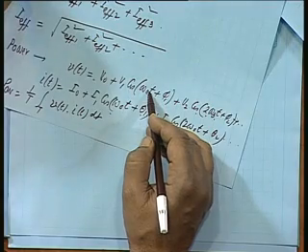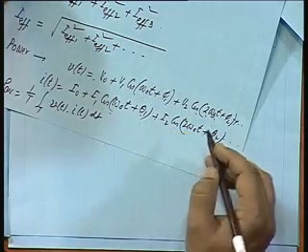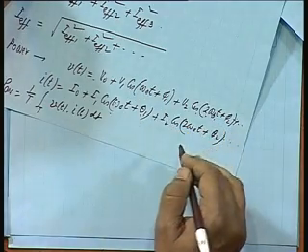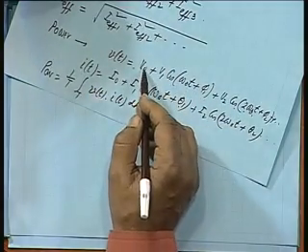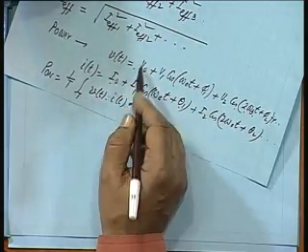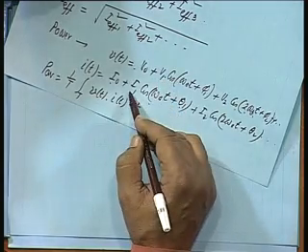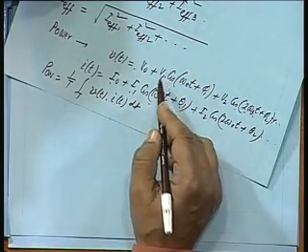We are taking the product of cosine functions of two different frequencies, then taking the average over one period. So, it will be 0 by the orthogonal property. So, cosine omega naught t will come with cosine omega naught t terms, cosine 2 omega naught t will come with cosine 2 omega naught t terms and so on.